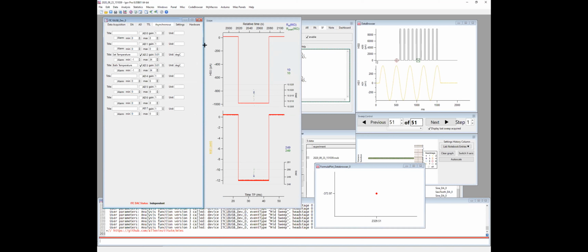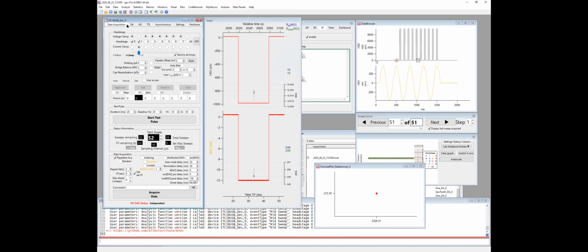You can also use multiple data acquisition panels at once, so if you have multiple ITC18s, or multiple NI devices, or an NI device and an ITC device, you can use them together. For some ITC models, we also still support using them synchronously. For NI hardware, this is solved on a hardware level, so MIES only sees one device. But for older ITC setups, we also support that.